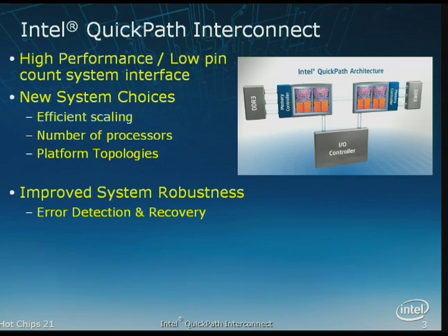And also, as Jose pointed out, if we look back at the frontside bus or bus-based systems, bit flips, parity errors, those were things that typically didn't happen, so therefore they were considered catastrophic events. As we go farther and farther and faster and faster, and the eye gets smaller and smaller, bit flips are going to happen. In fact, we don't even consider them errors anymore. It's just business as usual. And we must be able to identify those bit flips, recover from them, and continue on.